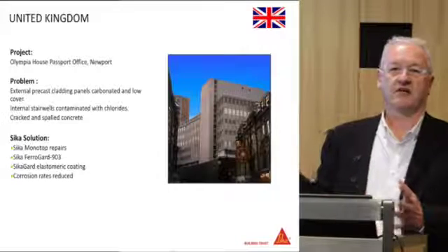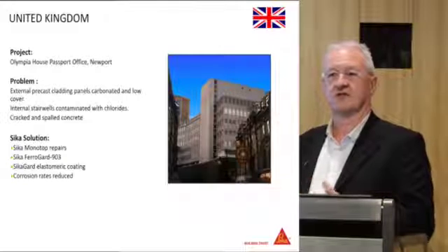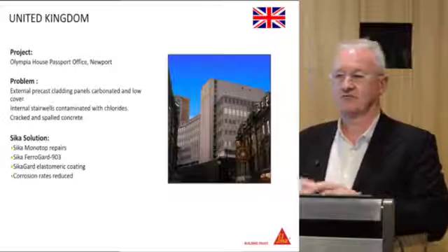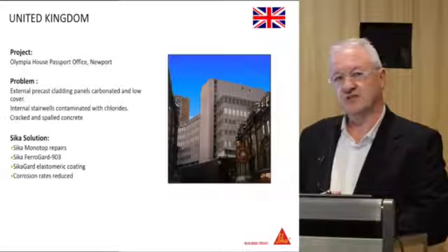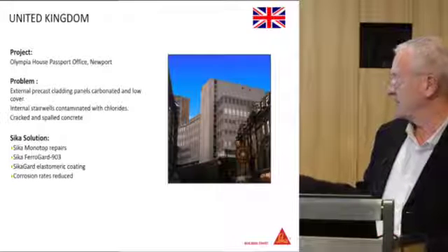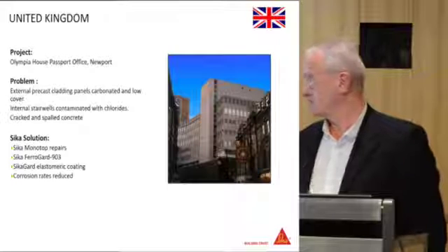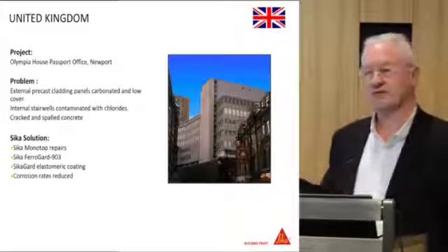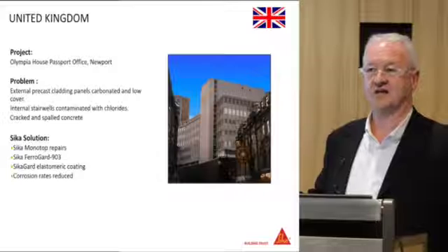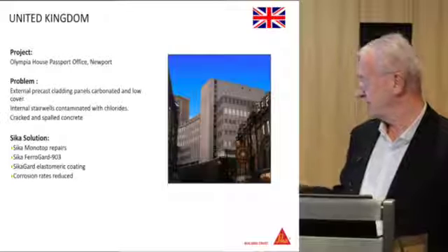Another way of doing it is to look at linear polarization methods, which actually measure the actual corrosion loss on the steel. I'm an engineer, I can relate more to how much steel's been lost than what voltage is going through a piece of reinforcement. So this to me is a bit more meaningful. This is you losing 158 microns of steel per year. And in BRE Digest 444, particularly with some of the criteria there, this is quite high. Things are happening now, and unless you do something about it, you're going to get concrete spalling off. So we did some pre-treatment in these areas.